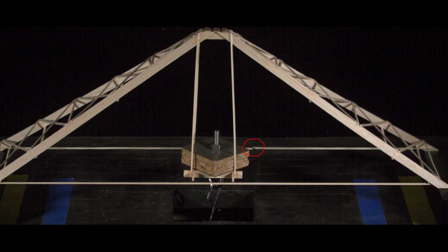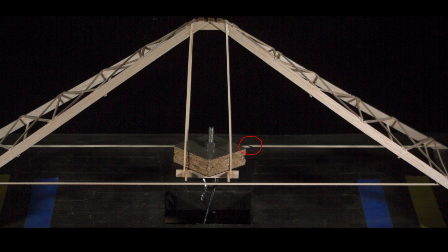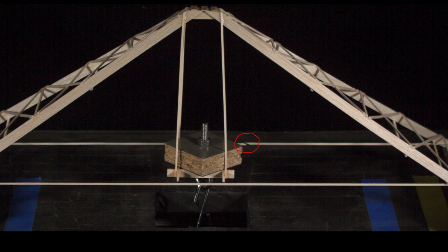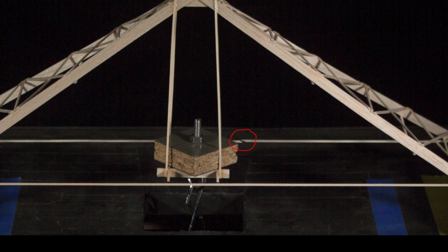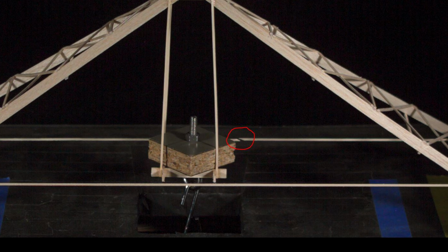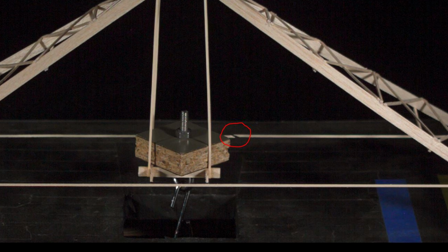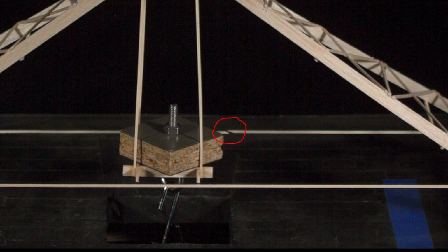I would say most people have a good feeling for the failure mode of tension, or the pulling apart of a piece. Here is a picture of a nice clean tension failure. You can see that the stick has literally been separated cleanly. With tension, as long as the piece has the same cross-sectional area and density, it will have the same tensile strength regardless of its length. We'll soon find out that that is definitely not the case with compression.